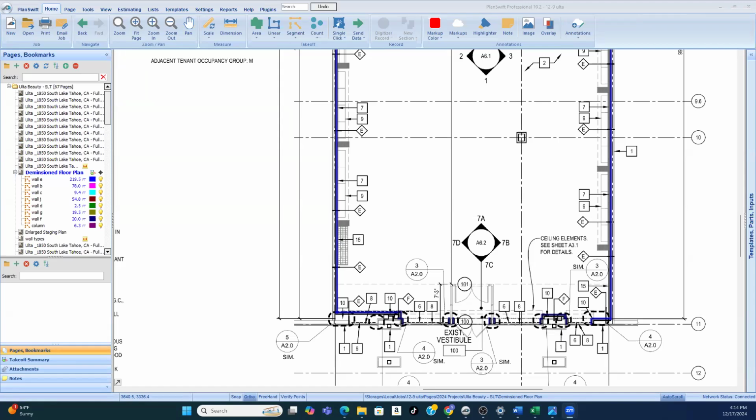Okay, so plumbing, if it's plumbing in a civil set, it stops at the building. And then the P plans are everything that's inside the building. So if we're talking about sewers, underground water, underground gas, all of that you're going to find only in the civil set. Once it comes into the building, plumbing and HVAC, you find that in the individual plumbing plan and in the individual HVAC plan.